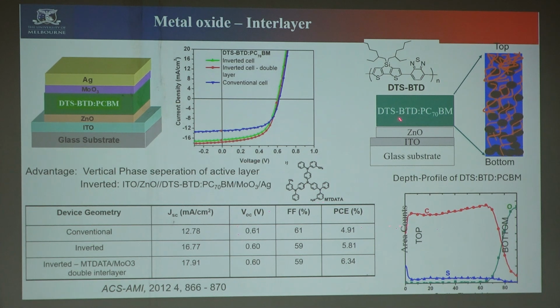What we did is we coat this material and take it into high vacuum and use argon sputtering. We can start sputtering, and when you sputter, we can remove the layer by etching 10 nanometer and study the Auger electron spectroscopy to see what elements are there. Like this, we can keep on etching until the bottom layer. This is around 80 to 100 nanometer. For every 10 nanometer we etch, we study what material is there. Like this, we can do the depth profiling.